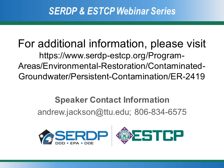Thank you. And can you tell us if there are lithologic constraints on the use of this tool? Is it limited to the use of direct push technologies? Yeah, so there are definitely some limitations. Clearly anything that can't be direct pushed is probably a problem, because drilling would make it very difficult to get the seal that we want, the direct contact between the sample cells and the sediment. You don't really want an annulus, because then you've got the potential for water to move up and down the sampler, and that kind of defeats the purpose.